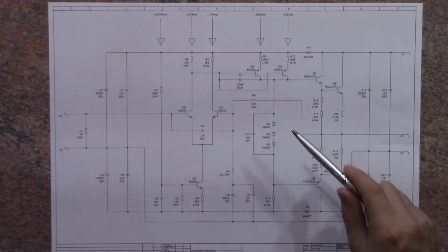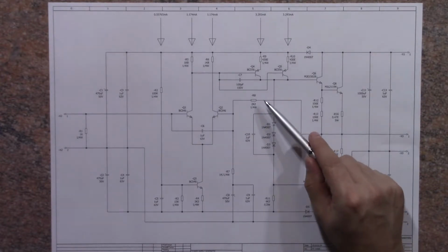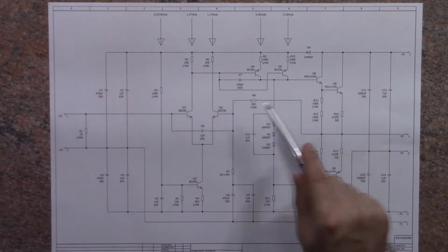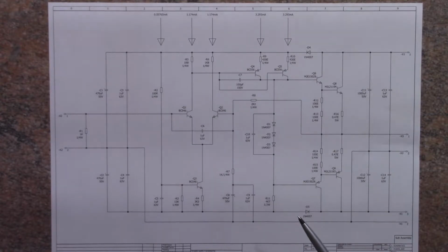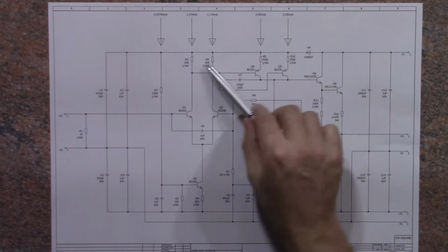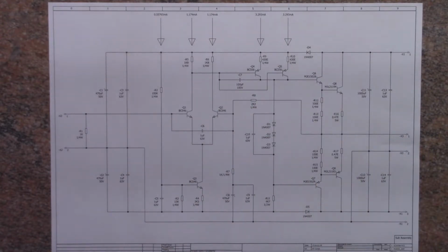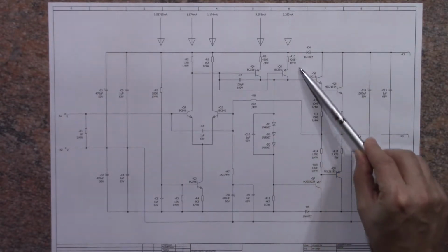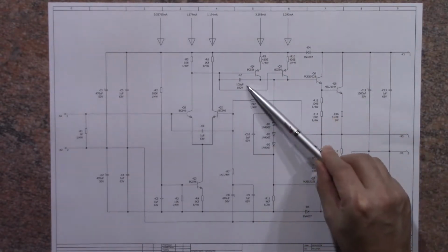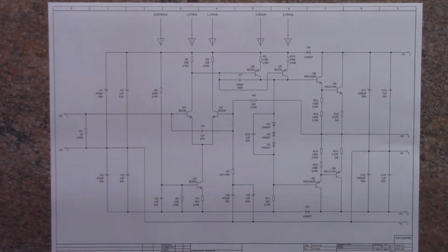The gain should always be fixed to a value much lower than what the operational amplifier as a whole can do. So in this case the gain is set to 3.2, and the operational amplifier as a whole has a gain of around 100. This extra gain is used to correct any errors that the amplifier might produce. This is called negative feedback. I've used 2 transistors here instead of 1 just because of the wattage requirement of the transistors.